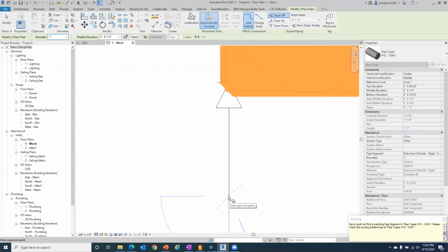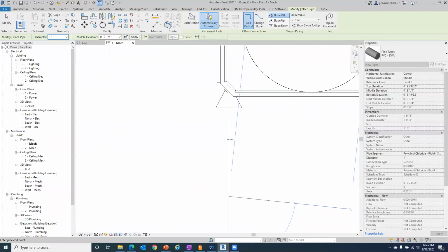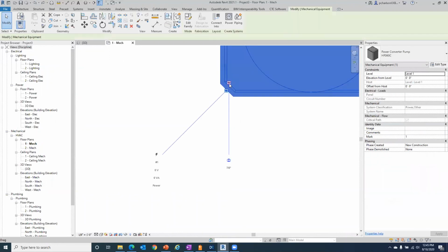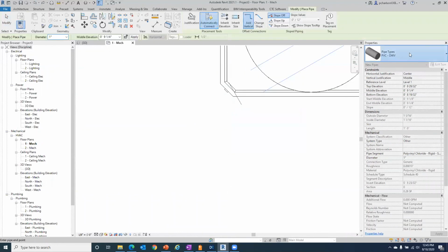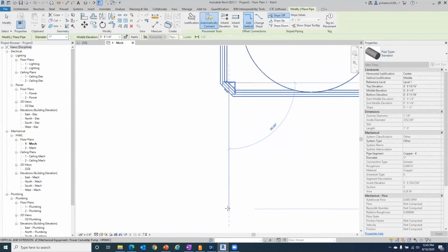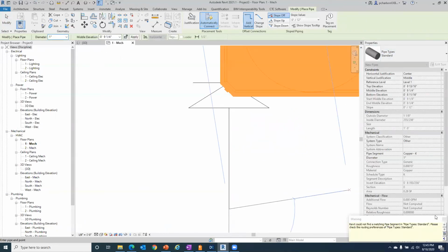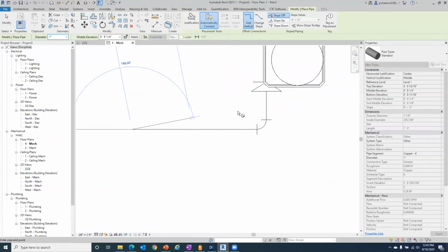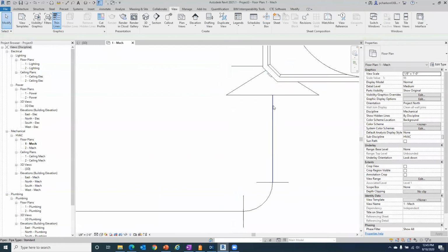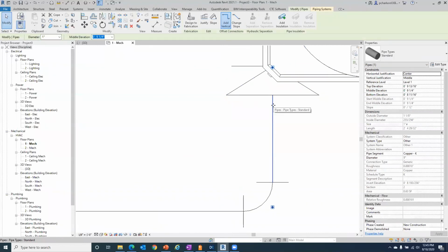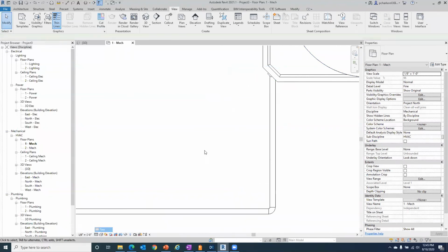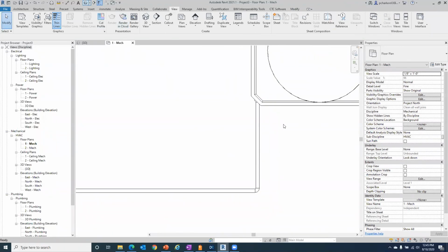So when I click on that, oh, I got PVC ductwork coming out of there. Let's try that again. Back that up. Draw pipe, and let's just do standard and see if that one works there. Oh, still doesn't like that one. I think it's probably just the size of that pipe coming out of there. All right, we'll go ahead and change this here to a fine mode. Let's see what's going on with that.